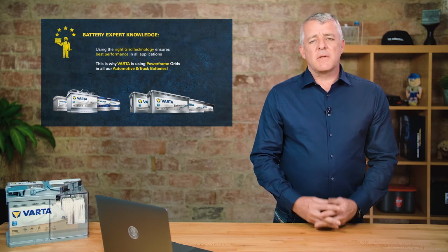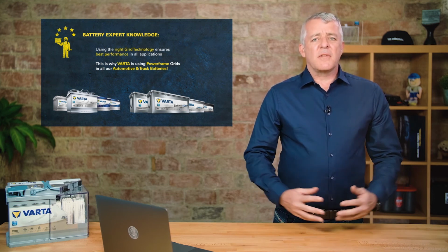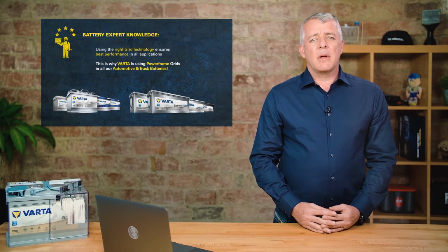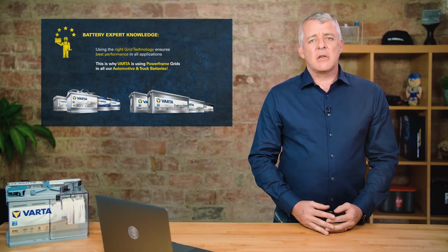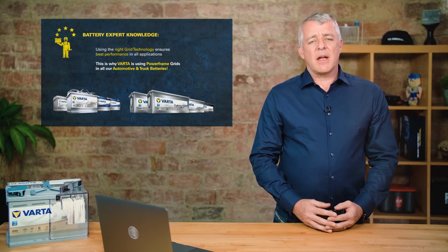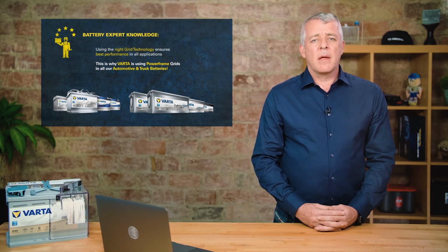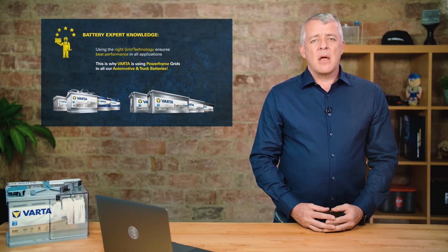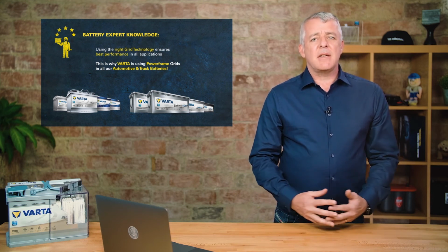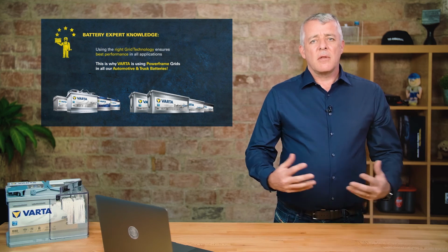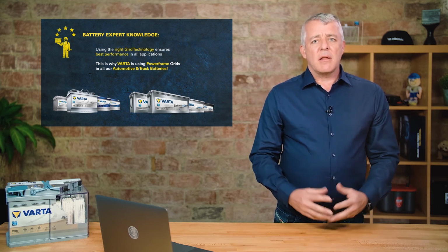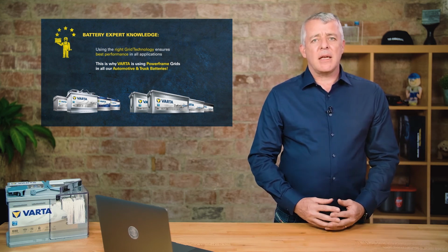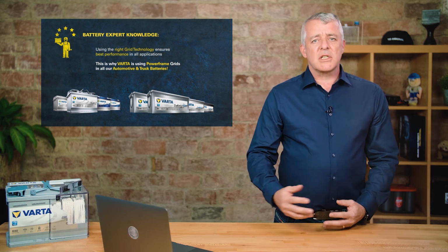This battery is used for long haul trucks where the drivers spend a long time away from the depot, so they use lots of consumers while they are parked up, such as a fridge, maybe a cooker or a microwave, and a coffee machine. As they discharge the battery, more and more sulfate is deposited on the negative plate. The more and more sulfate there is could make it difficult for the truck to start. With the truck AGM battery having a power frame on the negative plate, this ensures that the truck will start in the morning.